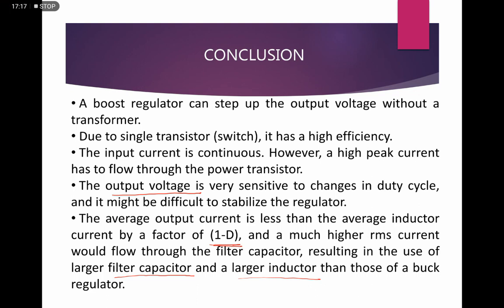This is the comparison between the buck and boost, if you have similar parameters, similar values of Vs, duty cycle and so on, and using the equations to find the value of inductor and capacitor, you can see that in the boost converter the values for C and L are bigger than the C and L in the buck converter with the same parameters.